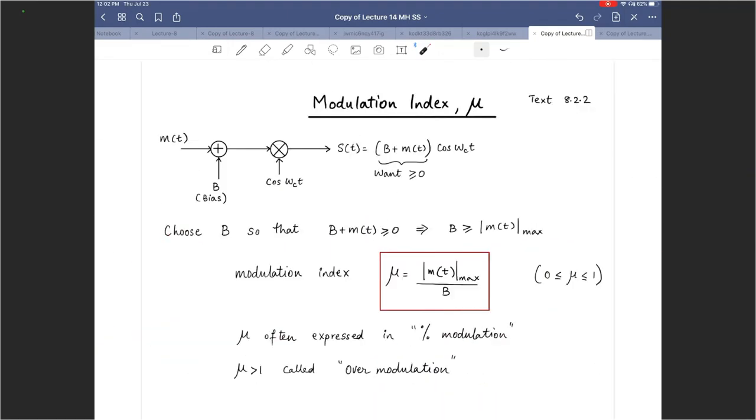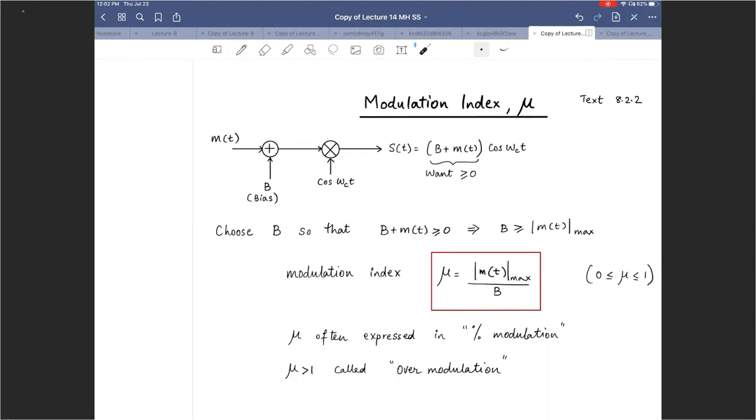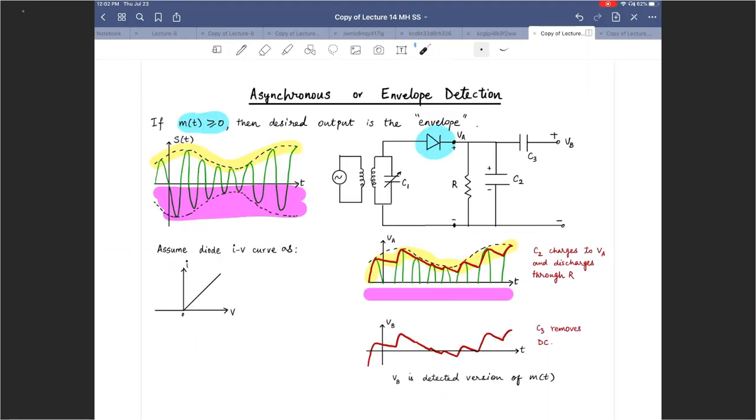So if we want to ensure that, then we can take a message, any message. It might be going down, it might be negative, it might be positive, whatever that is, any arbitrary message, and then we add a value B to it, some bias to it. And by adding this bias, we are pushing it up such that it will never be below 0, right? So that bias B is being used to push the signal up from here to there, right? So we are pushing it up.